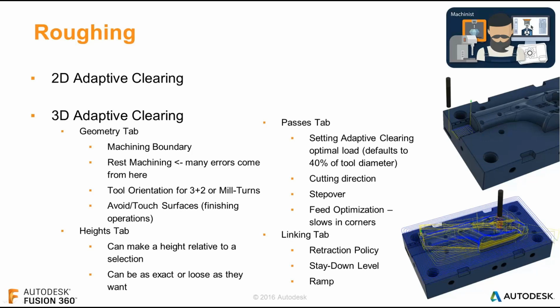For Fusion Ultimate, I mentioned before, it has very few differences from standard Fusion. One of those differences is multi-axis machining. So again, if you have someone who just has a Bridgeport and is only going to be cutting 2.5D, or they have a simple machine that's only going to be cutting 3 axis, they probably won't benefit from having Fusion 360 Ultimate. But if you're going to be training, it is important to make them understand which version of the software they're going to need. So hopefully they're saving money to give to you as training, which is great.